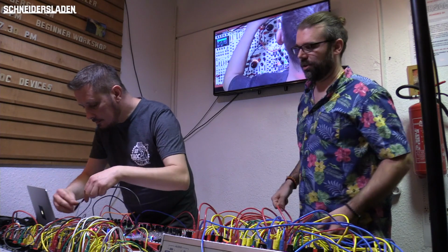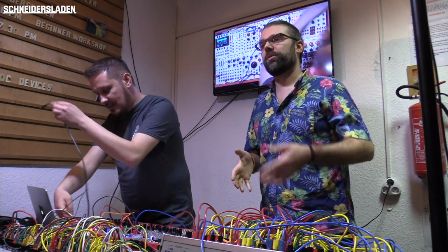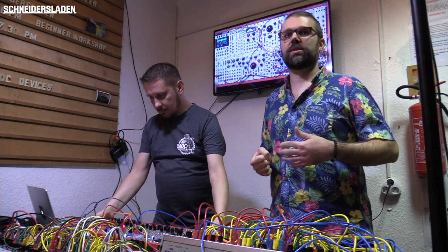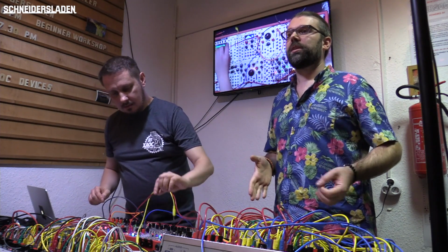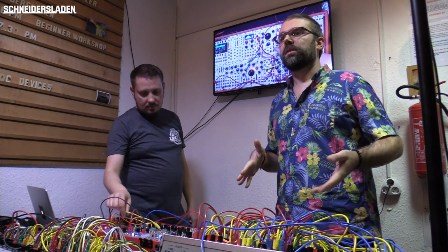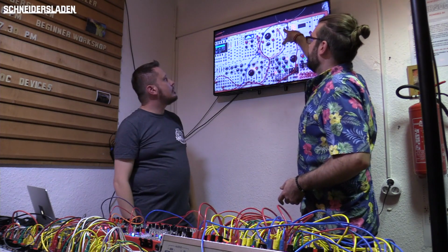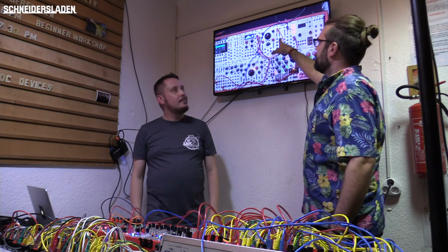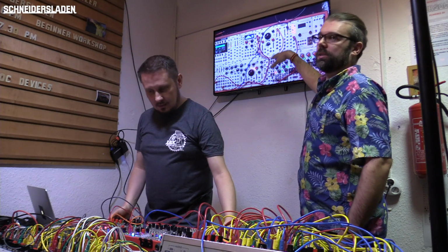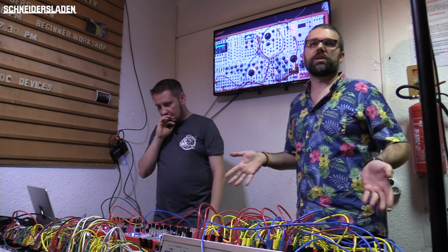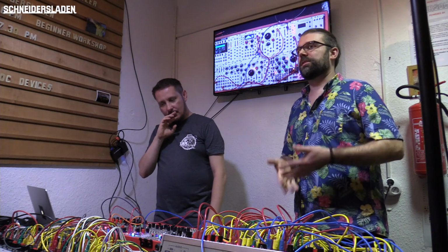They are really quick if you use the internal clock, because it's 2 megahertz, but you can slow it down to a regular clock rate, and it will act a bit like a sample and hold, holding the voltage on the output, but it will also let you have a slower sequence of these gates that are a representation of the beats, and you can use it just to trigger your drums, samples, envelopes, or whatever.